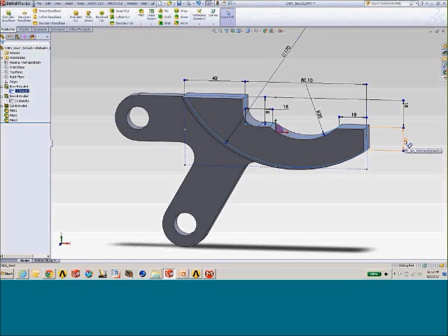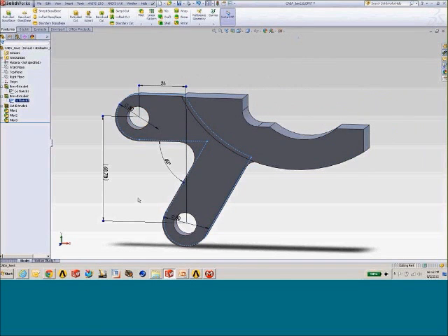Here's our jaw height over here. Here's the jaw outer diameter. We'll be bringing that across as well. And then for the additional 2 parameters, I'm going to go to my second sketch that I used to create these cutouts for the pivot points. And there's my horizontal, or what I call my pivot vertical, and my pivot horizontal. So these are the parameters that I'm going to bring across on the CAD side to the analysis environment.